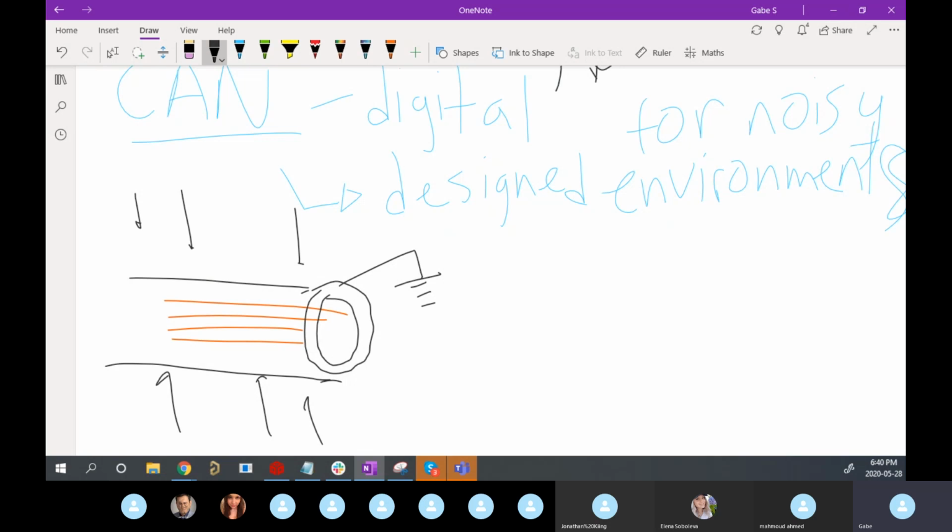This is what they call the shield. So usually shielded cables try their best to protect the signals that are coming inside. And you want to use this as much as possible for noisy environments, but it may not always protect it 100%. So usually it's the best you can do. We're going to have to do this on ours for a lot of signals, especially because we made a mistake, which I'll talk about in a second.